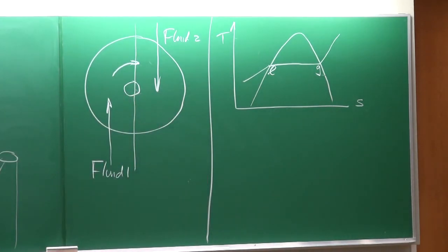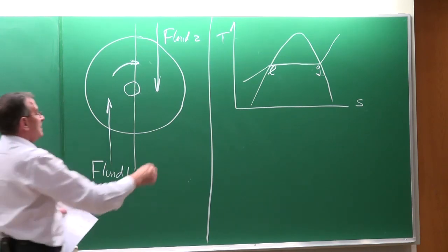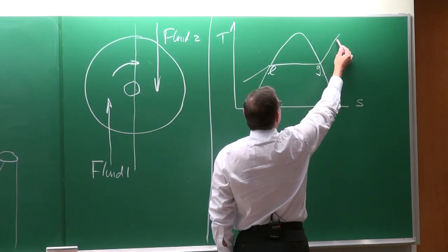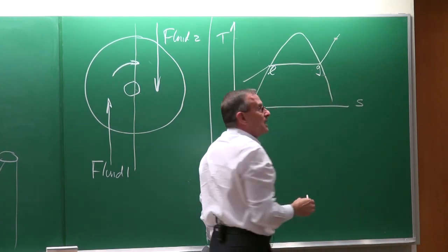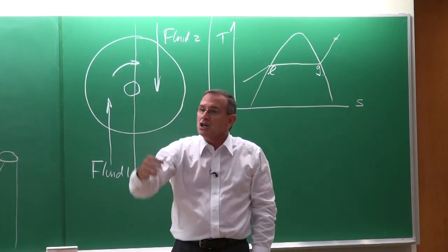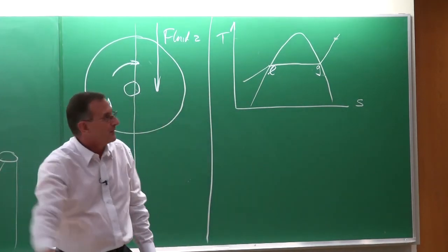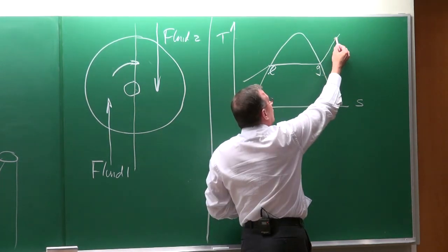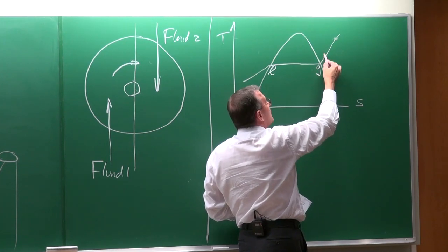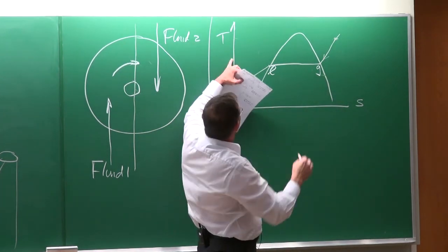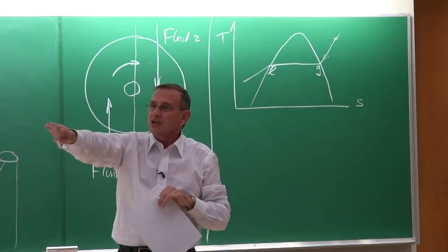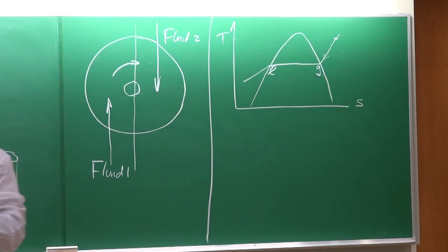So condensation would typically be, now let's suppose this fluid or gas has been superheated up to this point. If we would have that in a heat exchanger, any of these types of heat exchangers, and this is now the hot side, and it is being cooled, what you will see is it's going to move down there. Okay. What happens with the temperature when it moves down there? The temperature decreases, just like I've shown typically for the parallel flow heat exchanger and the counterflow heat exchanger.